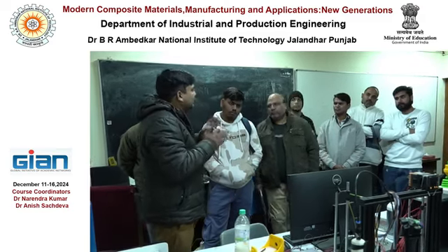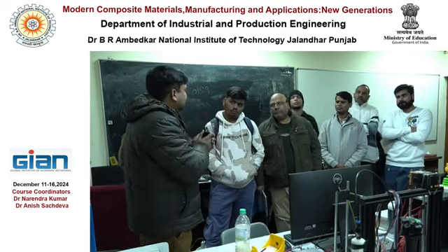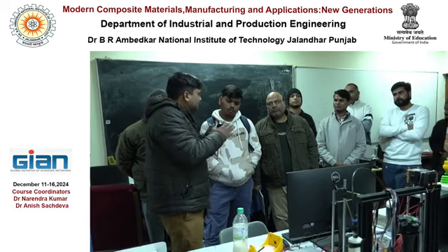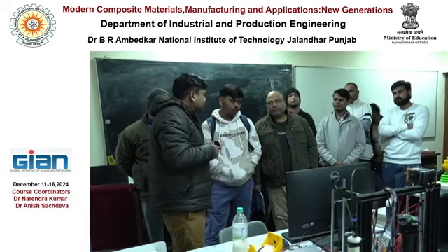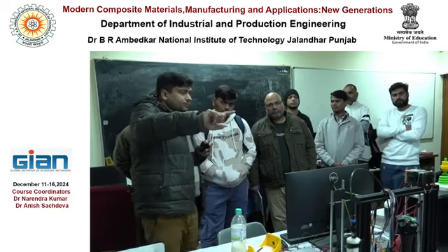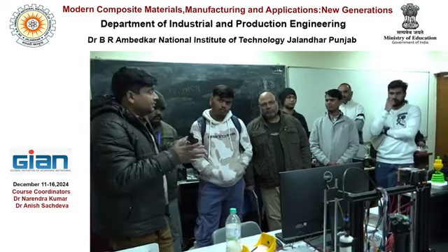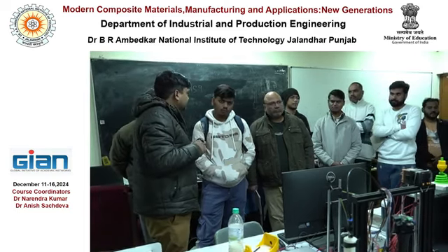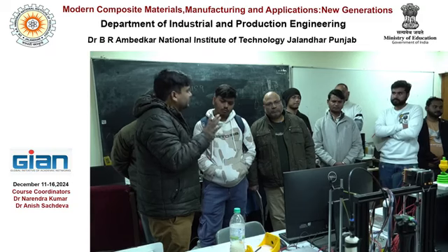We should avoid more joints within the specimens, because our objective is to make a part with adequate strength, right? Adequate surface toughness. So we can decide the specimen orientation by using our wisdom and the requirement. So the operator will decide.